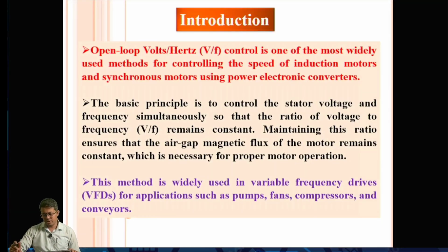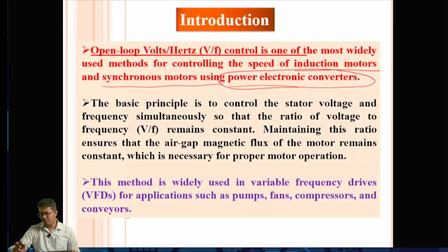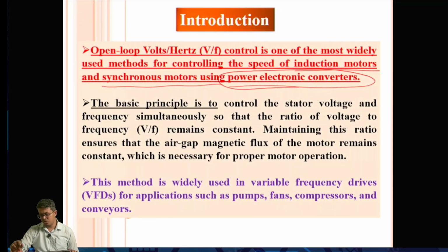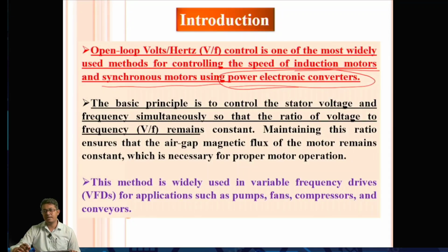So let's understand elaborately what this V/F control is. V/F control is open loop V/F control. It is mostly used for controlling the speed of induction motors and synchronous motors also. By connecting some power electronics converters, that may be an inverter, a rectifier, or a cycloconverter. The basic principle is to control the stator voltage and frequency simultaneously, so that the ratio of V by F remains constant.